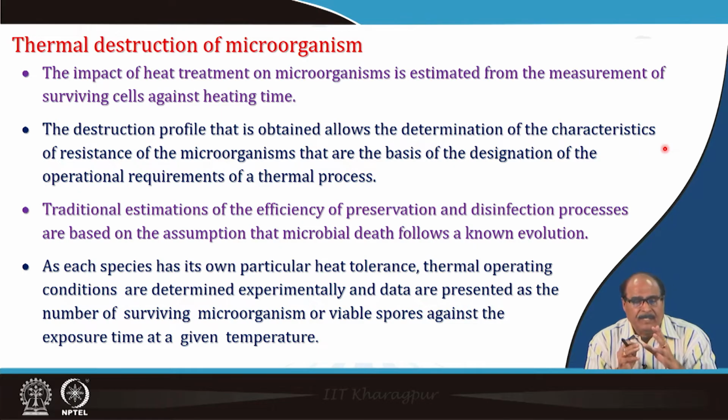The impact of heat treatment on microorganism is estimated from the measurement of the surviving cells against heating time. The destruction profile that is obtained allows the determination of the characteristics of the resistance of the microorganism, which are the basis of the designation of the operational requirements of a thermal process.